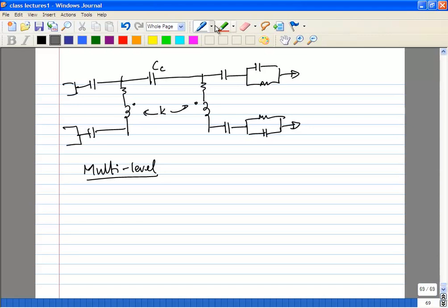From the biasing supply. Exactly. If you take power amplifiers, you will often see circuits biased such that you have an inductor from VDD to the transistor. So for example, you could see something like this. And let's say you have some resonant circuit, matching circuit, whatever, and this is your load resistance. So you could perfectly well have a case where you're really not interested in the Q of this inductor because you're not using it as a resonant circuit.